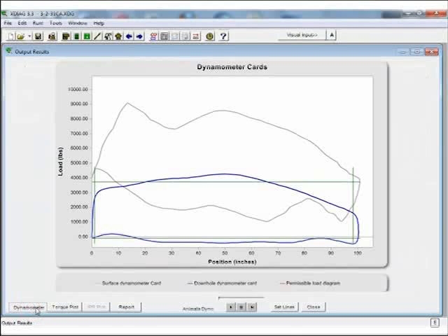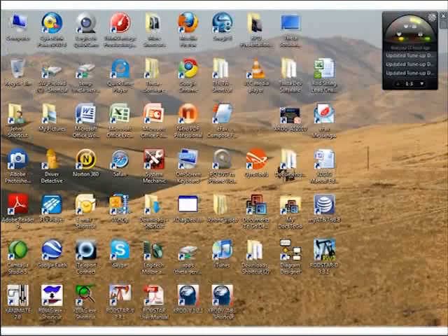And also the calculated pump displacement is higher than the production, which may indicate that there might be a tubing leak. Now if you take a look at the dynamometer cards, this is the surface dynamometer card, this is the downhole card, and as you can see, it looks like a leaking traveling valve, but because this is a group 2 well, that may not be what's going on. Actually the program says that it's a full card, so it's normal to have this shape. Okay, so that's the first step, and then we save this XDiag file, and then we can go into RODSTAR.